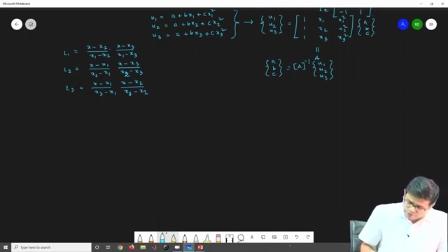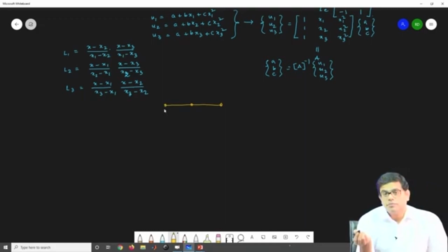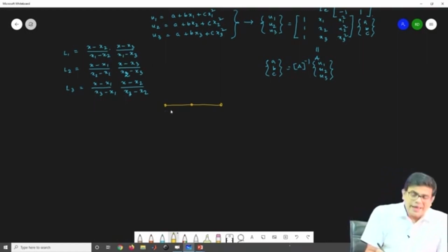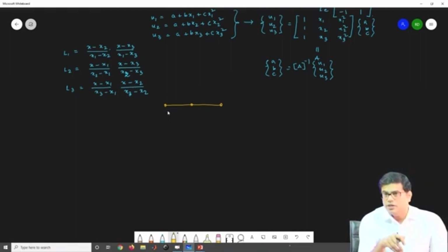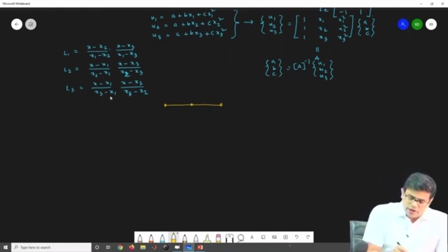So now to simplify it in the local coordinate system, let us do a local system which is this, where, instead of a general coordinate system, let us first assume that node 2 is the mid node, at the midpoint of the element. Then I can just choose any point and derive this shape function. So this is very much just putting in the coordinates. In the local coordinate system, this is 0, this is LE by 2, and this is LE.